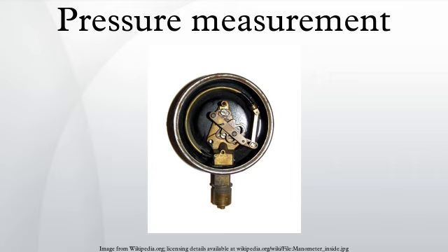Hydrostatic gauges compare pressure to the hydrostatic force per unit area at the base of a column of fluid. Hydrostatic gauge measurements are independent of the type of gas being measured, and can be designed to have a very linear calibration. They have poor dynamic response.